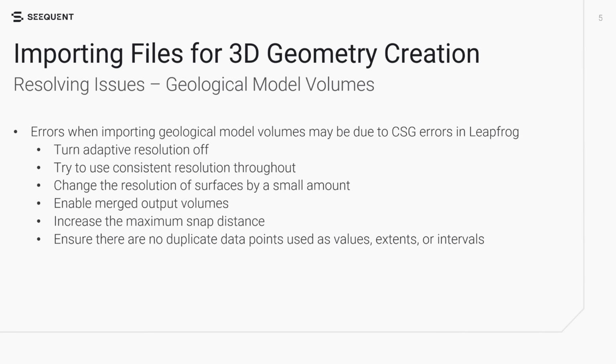Although it can be challenging and in some cases impossible, whoever is constructing the 3D geometry in GeoStudio needs to have better control over how the upstream geometry is being constructed. Depending on what application is used to generate these files, there are different approaches for resolving import issues.